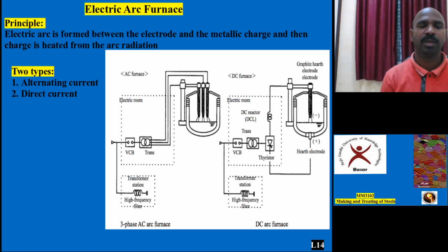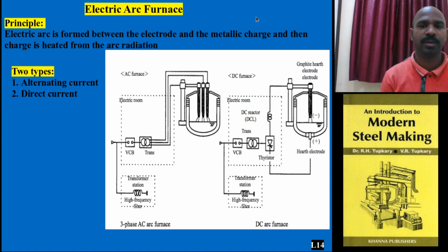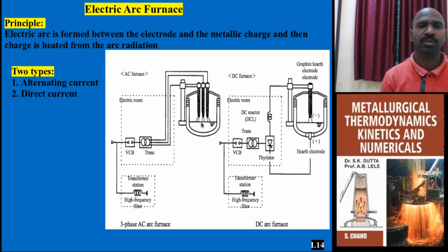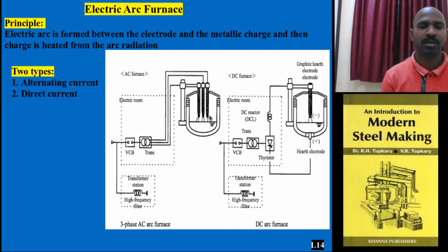Today I am going to talk about the principle mainly involved here. An electric arc is allowed to form between the metal charge which was poured here and the electrode, so that the electric arc radiation develops. The radiation slowly heats up, and that heat build-up rises to a temperature to melt the corresponding charge, such as steel. If it reaches around 1600 degrees Celsius, meltdown starts.